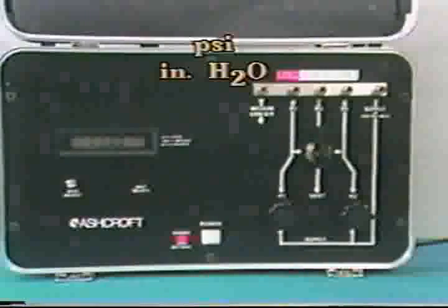Regardless of the application, the same calibration procedure applies for any differential pressure level measuring system. A low-pressure calibrator is the input measurement standard for this setup. It provides and measures the low-pressure values typical of differential pressure. A low-pressure calibrator contains both a regulator and a pressure transducer in one package. This calibrator displays pressure on a digital display. Pressure is shown in either pounds per square inch or inches of water.